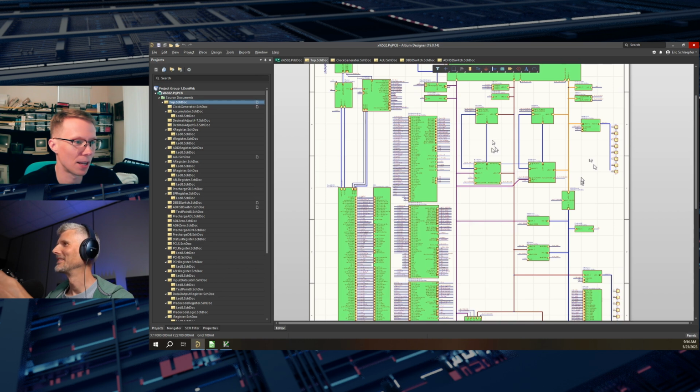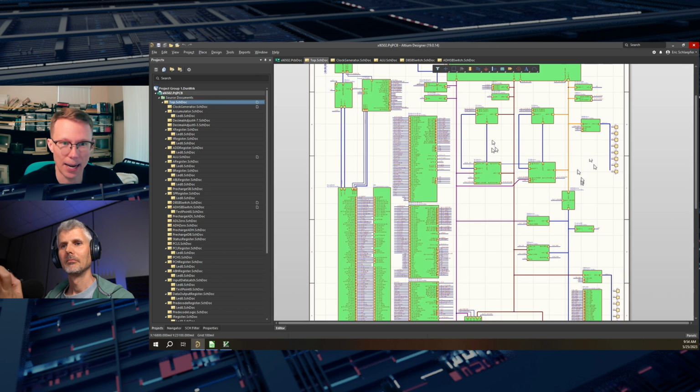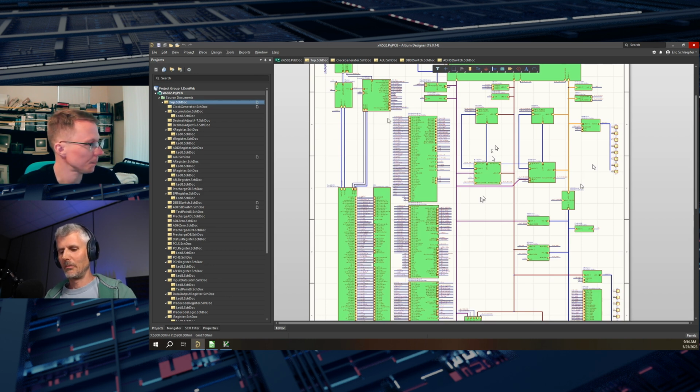Yeah. I guess I would say that's the other challenge, is that this design is, besides being fairly archaic, also dynamic, which is a real problem, because that means that there are dynamic latches scattered around everywhere. So we're storing our state information literally in the gate capacitance of inverters and other gates. Yeah. So that means we can't even stop the clock. Do you want to just explain what a dynamic latch is compared to a full latch?